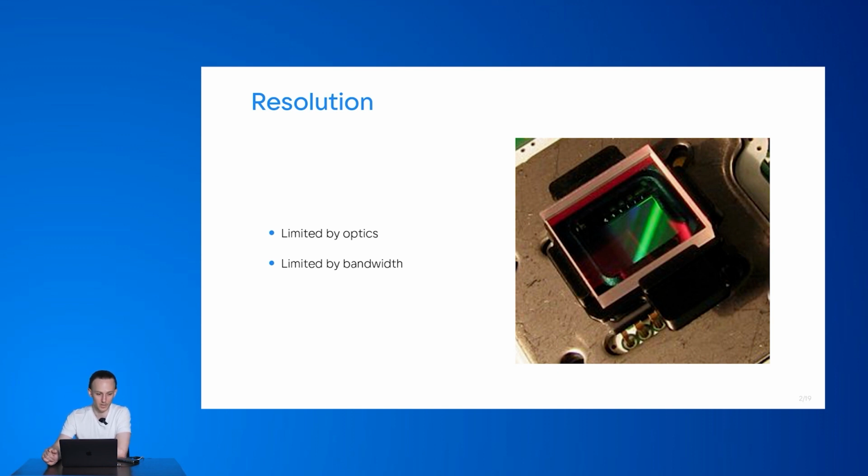If we try to make our photosensitive elements smaller and smaller, at some point we will not be able to do so because it will stop making any sense. If we make our sensors smaller than the wavelength, they will not register different waves, and that's it. So the sizes of the photosensitive elements, the photodiodes, are in the range from around a micrometer up to tens of micrometers, maybe 40, 50, something of that kind. But that depends on the type of the camera, the type of the sensor itself, and the purpose of the camera.